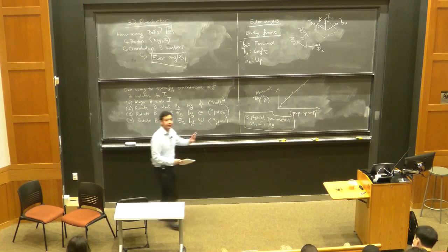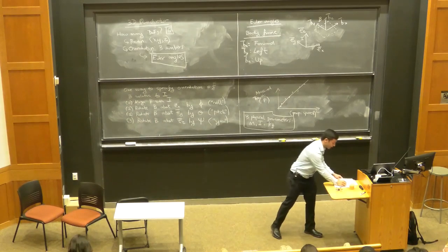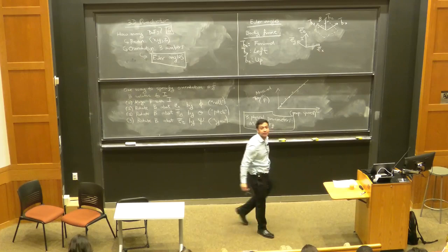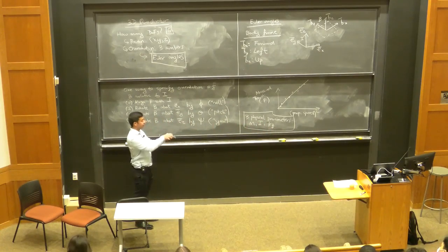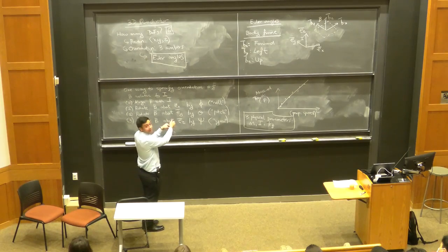All right, so let me just illustrate it once maybe with the physical drone. I also have these Wolfram Alpha demonstrations, which I think should be pretty useful if you haven't seen this before. So again, you start off here, rotate about the inertial x-axis. So that's the roll angle. You then rotate about the EY direction. So EY, remember, was to the left. So I line my thumb along the EY direction, and I apply the right-hand rule. So that goes this way. And then EZ again goes up. I align my thumb with the EZ direction, apply the right-hand rule, so that goes like this.